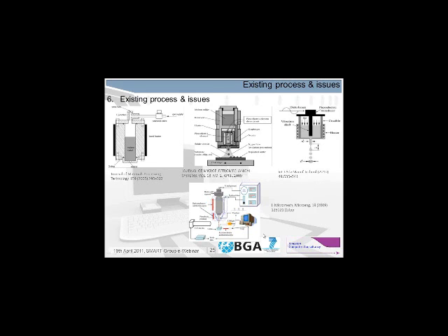And finally, this system here in colour at the bottom shows, I suppose, the current state of the art for many systems: your core solder ball production system using a nitrogen environment to maintain pressure and transducers to maintain consistency of solder balls. But you can see here a CCD camera, some sort of imaging, some sort of lighting system, and then feedback into control systems, so that the entire process is becoming far more automated.